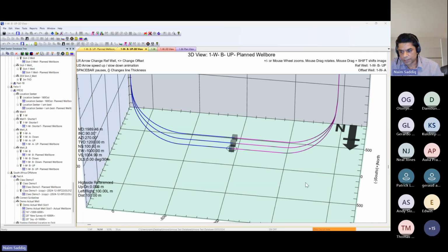Sorry, I have to probably show you first the hole cleaning chart. The requirement to clean this hole will be 610, but you cannot pump that much because the standpipe pressure will not cope. And you can actually play with the software and solve the problem by changing the casing sizes interactively. At one point you will be able to solve it.